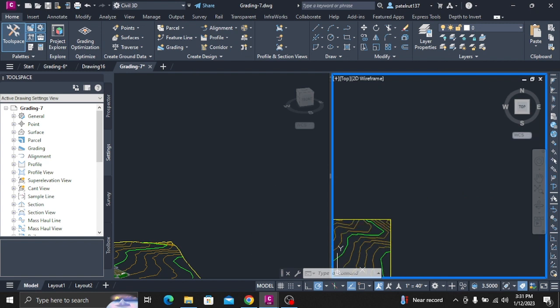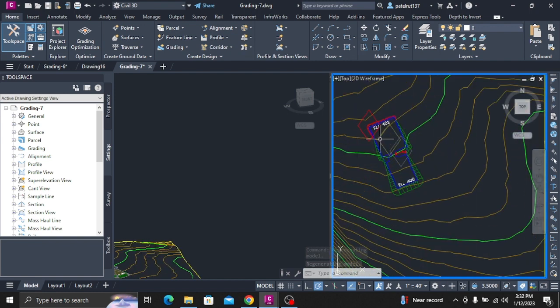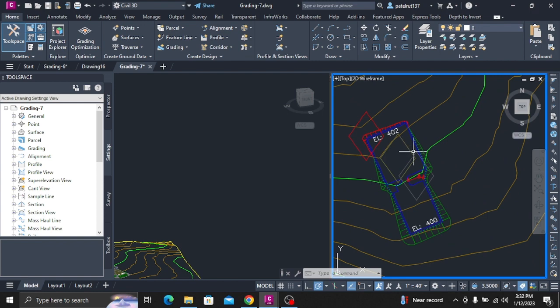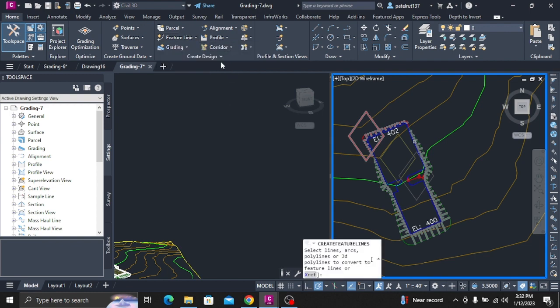Locate the row containing the icon. Notice that the value in the elevation column is 402.000 foot, which is the same value you entered for the other feature line in Step 4. Change the elevation value to 405.000 foot. In the left viewport, notice that the value you entered for the shared vertex updated the elevation of both feature lines.